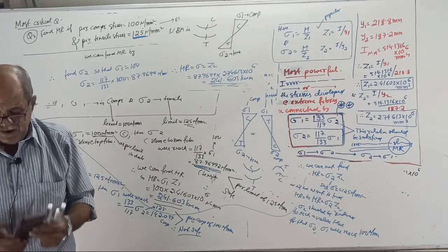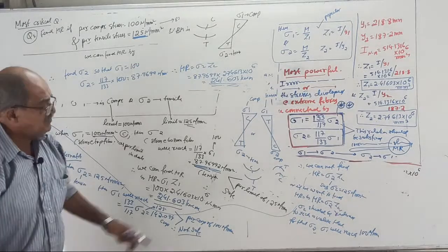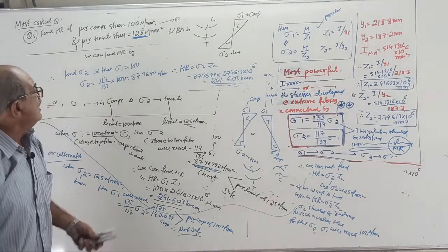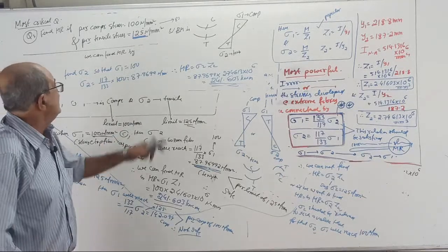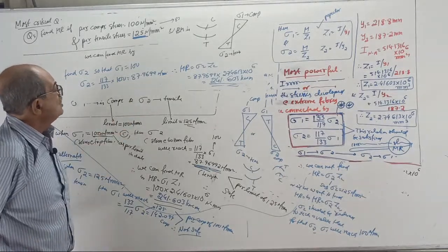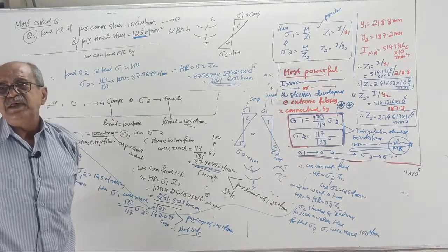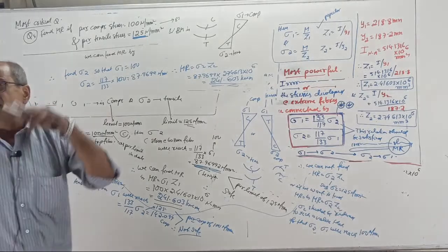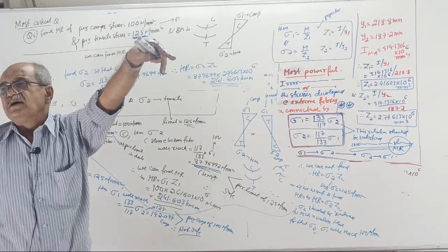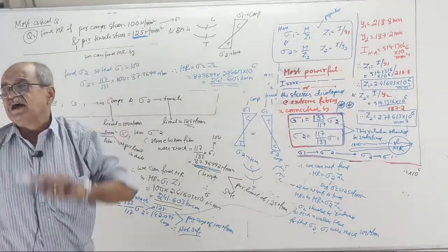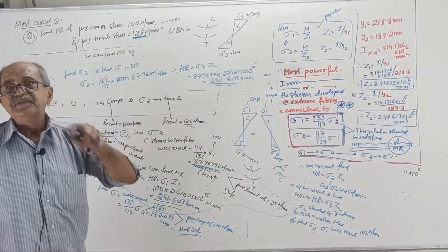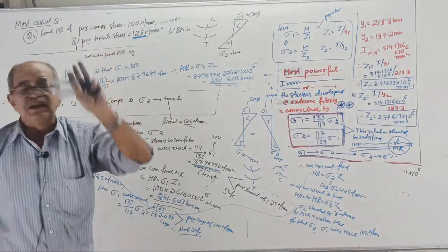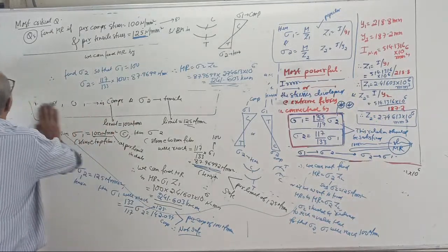So, irrespective of whatever you do, the answer is the same. Now, therefore, MR for this cross section is 241.603 kilonewton meter. Actually, this is based on what? Compression limitation, correct? This is based on compression limitation. Now, one homework I will give you.